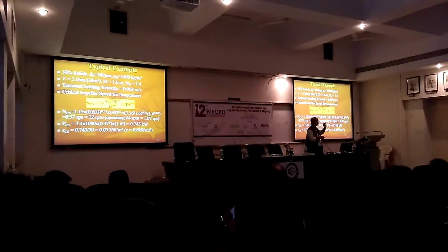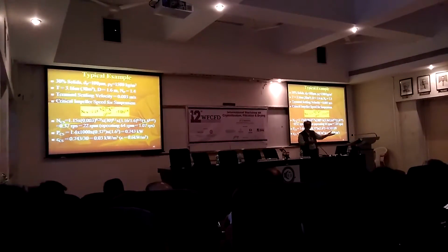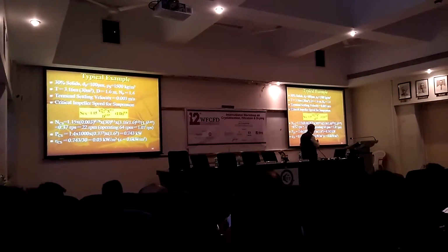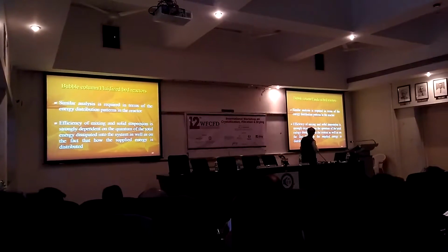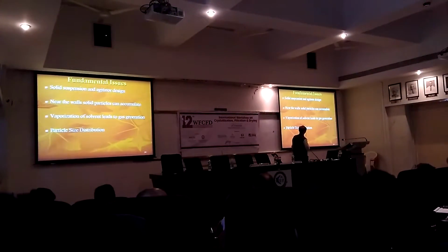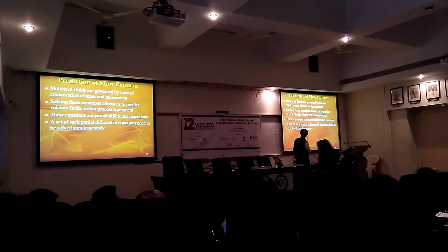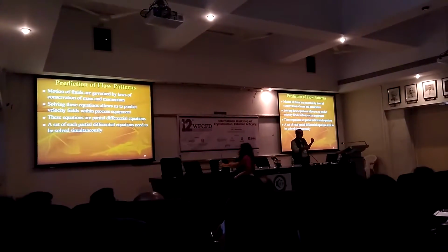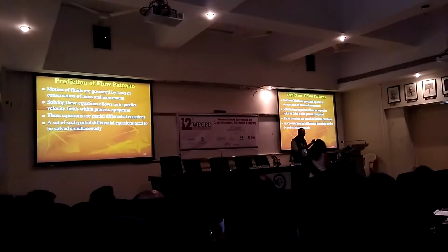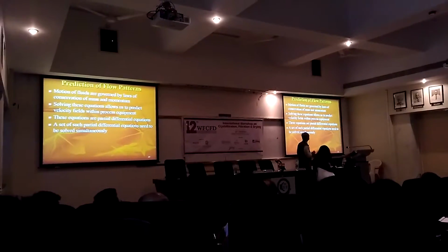The constant varies, which is a function of geometry, size, type of the impeller, location of the impeller, and so forth, and a lot of data is available on this. Different types of equipment can also be used. So how do we handle the near wall solid particles that can accumulate? Indeed, we need to have computational fluid dynamics essentially to be able to address this particular issue.